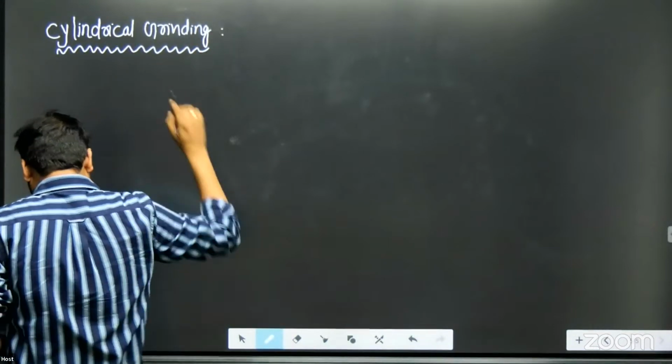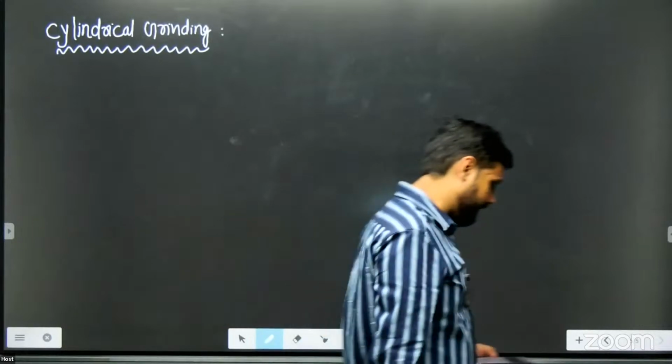And that centerless grinding that I told you now is of very high importance for the upcoming GATE exam and other exams, I can say. That formula, always remember: feed equals pi D N upon sine theta.